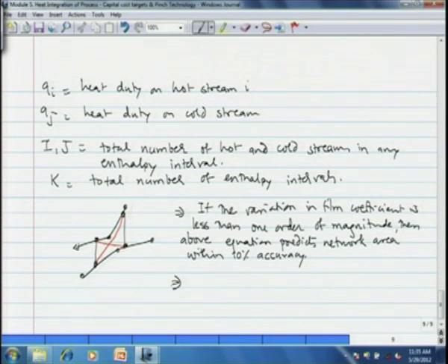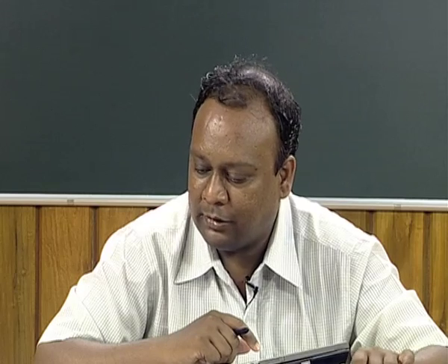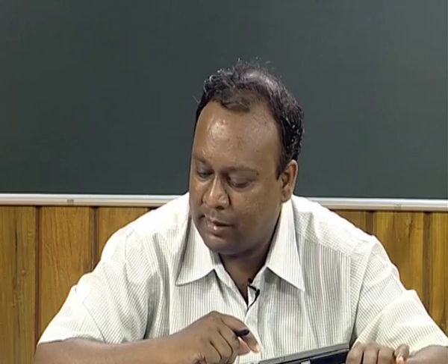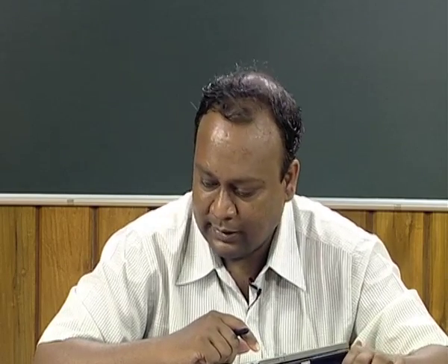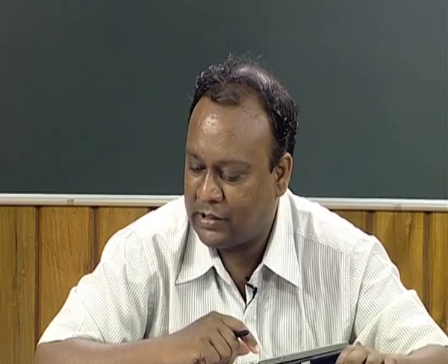Now, network designs usually do not approach the minimum, as the true minimum designs are too complex, and significant reduction in complexity requires only a small penalty in the area. The area targets being predicted here are used for pre-design optimization of capital and energy trade-off, and evaluation of alternative flow sheets. Thus, the area prediction that is used here along with the capital cost data for exchangers have a considerable degree of uncertainty. Moreover, the capital cost predictions obtained from the above equations are likely to be more reliable than the capital cost prediction for major equipment items.